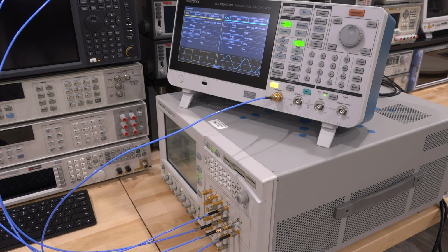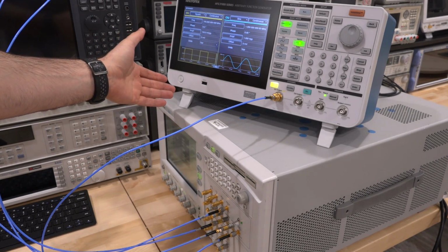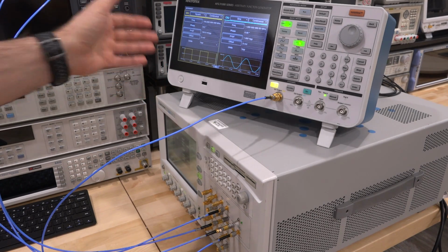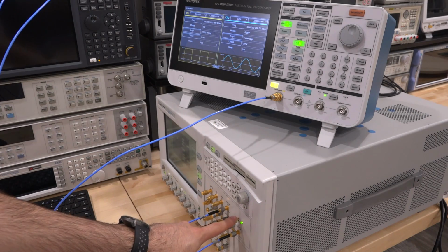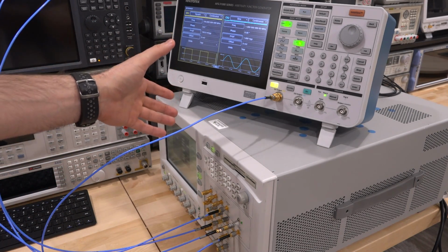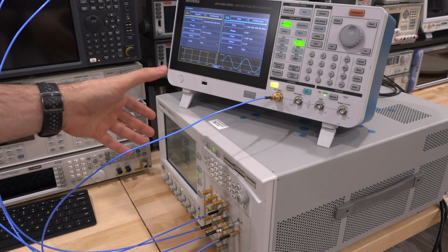So here's our setup to look at the jitter on the eye diagram by introducing jitter ourselves. I'm using the Tektronix AFG31000 series in order to introduce a 100 megahertz square wave directly into the delay control line input, which I can enable and disable with the switch that I have installed here. So this means that I'm going to apply a 100 megahertz jitter into the eye diagram. That's the jitter composition.